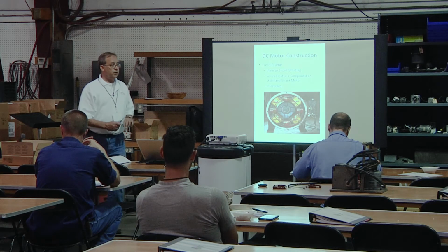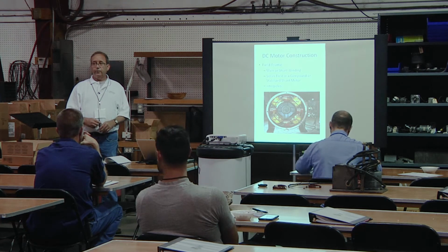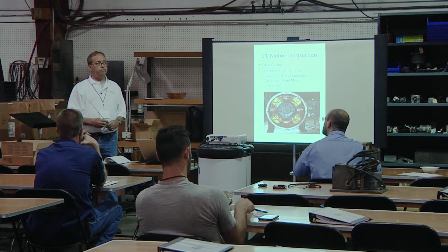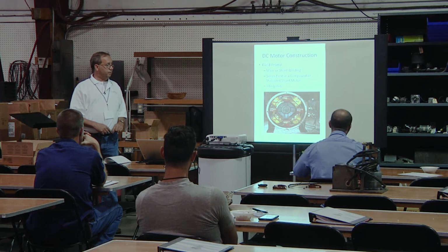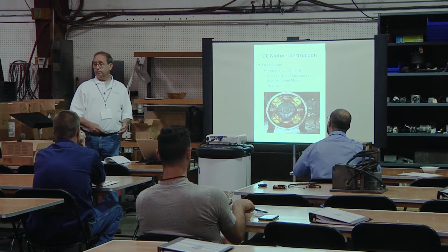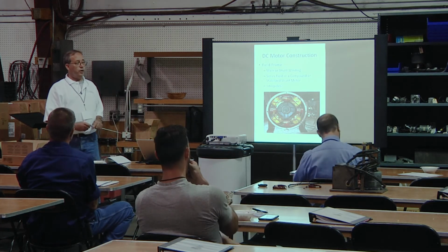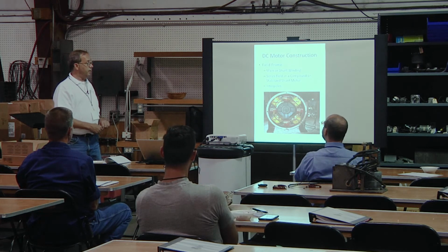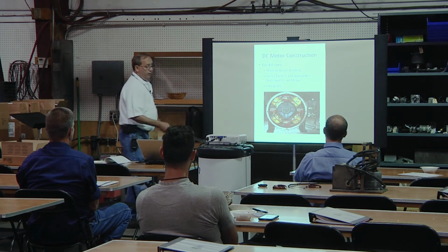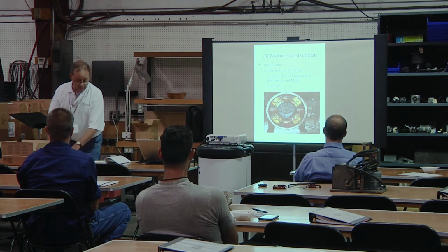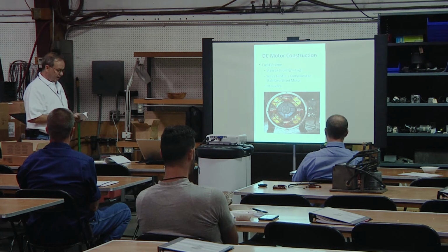We talked about the series field canceling out the shunt field. And if that happens, that's really no different than having a shorted field or having one with low or no voltage on it, or low or no current on it. And because that's wound on top of that, the polarity of that thing needs to be the same.